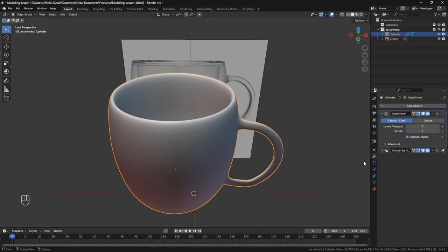So as you work in, let's say, motion design, there will be a lot of objects. So you just want to know how this model looks. So you can just make it the minimum, let's say one, two, or maximum three. In the second option, the render, you can increase it as much as you want. So in the viewport, you can say, hey, this looks good, but I want more. Then you can increase the render option. It's two here. You can increase it to three, four. In the render, it will increase the polygons. Exactly, it's just a preview. Yeah, you got it.